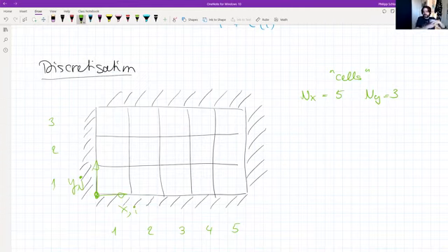So now I have distributed my domain into cells. But the next step is, since we are going to use a staggered mesh, as Ardashir was already introducing, we also need to know in what points we actually define our velocity components and the pressure components. And the idea now of the staggered mesh is that the velocity components are not all defined in the same physical place. They're all related to the same cell or element, but they're not in the same physical place.